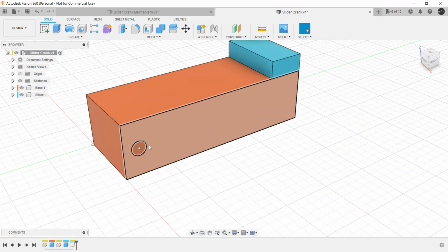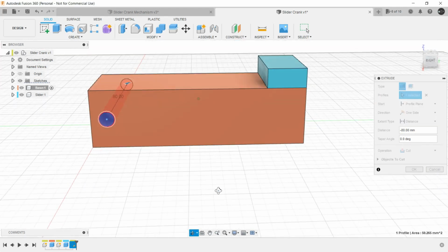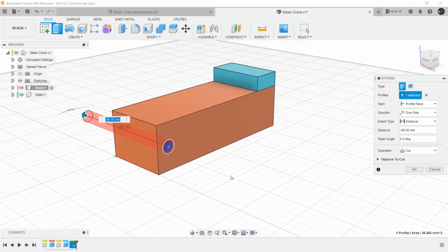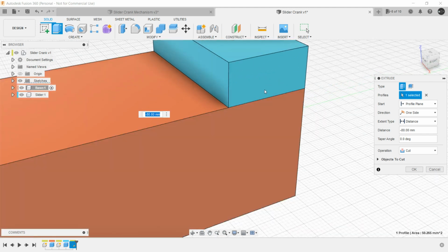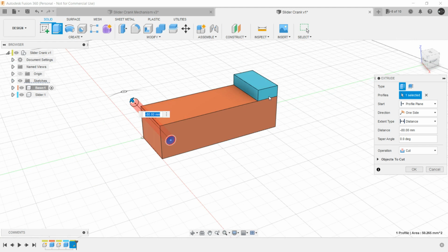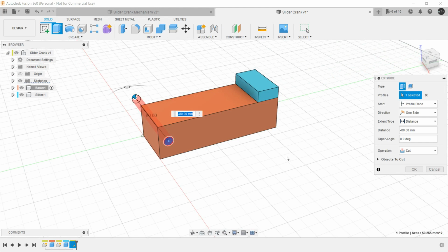Finish the sketch and let's select the region and cut it through so that we can put a pin in this one. So notice the changes that we are making in this component are not making any changes on this component because the sketch entity is very far away from this one. But if this sketch entity was somewhere between this junction, then both of the components could have got this through cut. This we have seen in previous assemblies as well. So just press on OK.